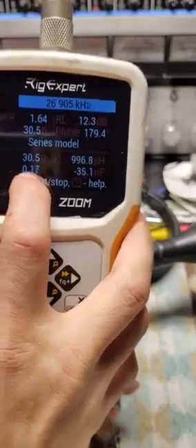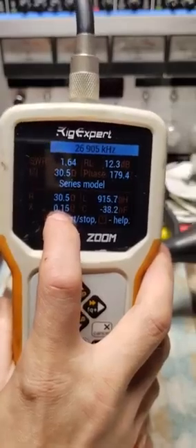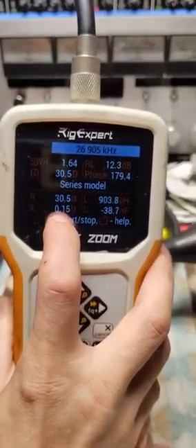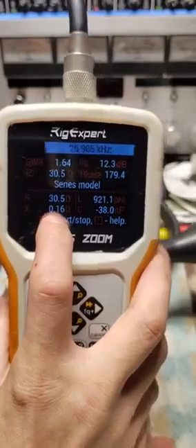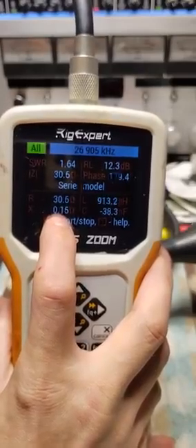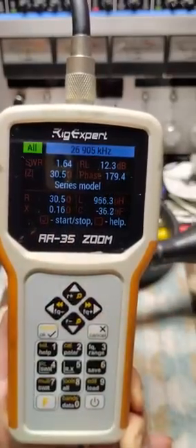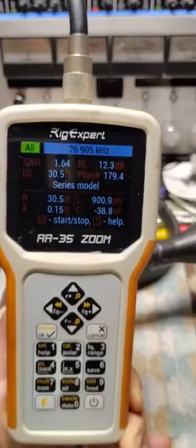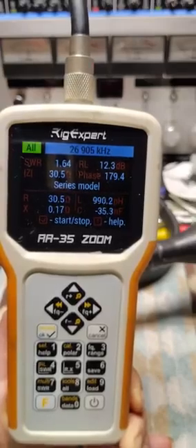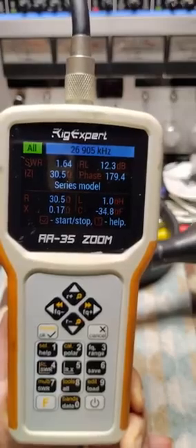Once the antenna is tuned with a half wavelength piece of cable and there's no more reactance at play, once the reactance is gone, the feed line will no longer act as an impedance transformer, so long as you've got the feed point of the antenna at 50 ohms through that half wavelength tuned piece of cable with X factor 0.